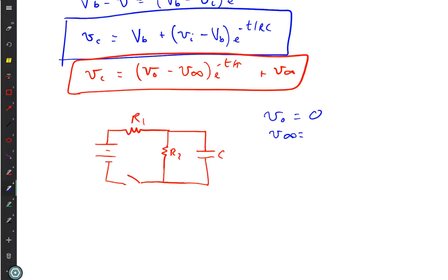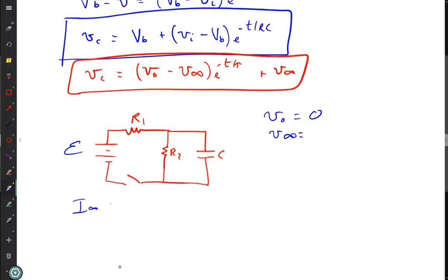So if I look at that circuit, I can ignore the capacitor for the infinite time and just say I have these two resistors with current flowing through. And so I could just solve it. I have a power supply, R1 and R2. Those three of you who've taken circuits know instantly, oh, that's a voltage divider. What's a voltage divider? It's when you have resistors in series and you just look at the voltage across one of them. In that case, the current at infinite time is equal to the EMF divided by the total resistance, R1 plus R2.